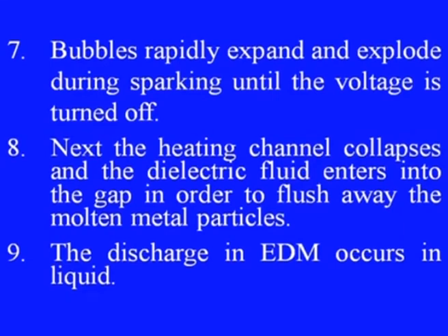The discharge in EDM occurs in the liquid. The single spark theory is inadequate to explain the discharge. More recently, researchers have used electrothermal, electromechanical and numerical methods to explain the dynamics and nature of the EDM discharge process. Maybe some more new dimensions will be given to this understanding of the EDM working principle.